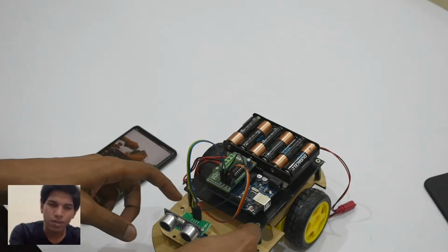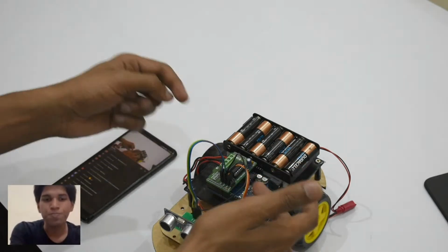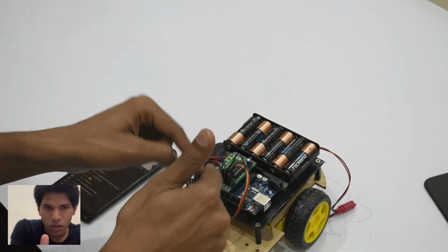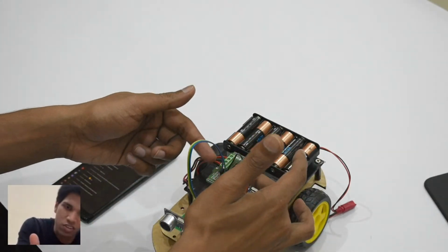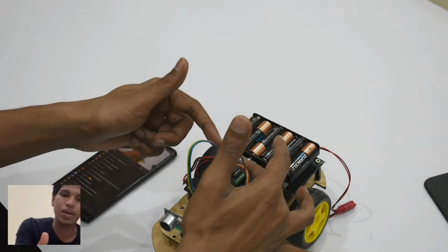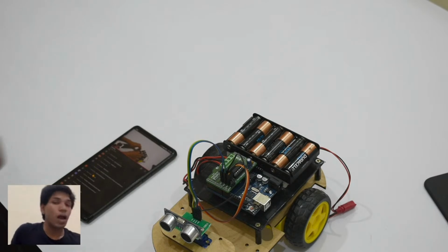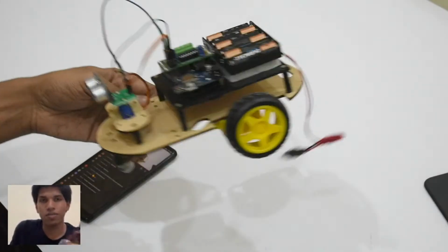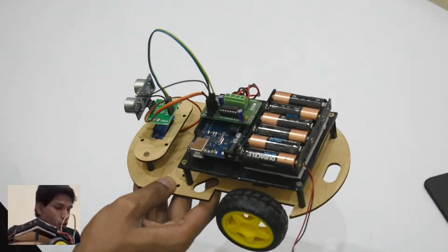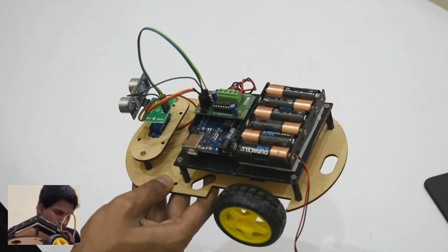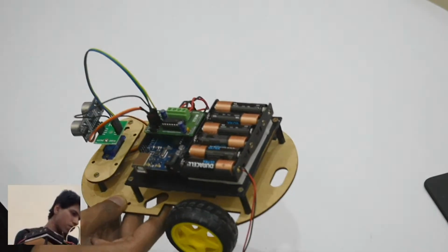We have connected the data pin of our servo to pin number 9, the echo pin of the ultrasonic sensor to pin number 8, and the trigger pin to pin number 7. And then the rest are just 5 volts and ground supply, so we have connected them to the 5 volts and ground pins. That's all we have done. Okay. So now we are going to code this. But before we code this, since I have the code added, my voice is low.